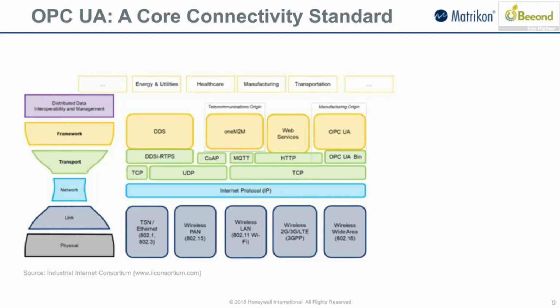And of course, there are different uses for different standards depending on what you're doing, whether you're doing fully engineered software systems, which would be more towards the DDS side, or you're doing more third-party ad hoc connectivity, which is typically what you see in plants and manufacturing environments, where you're bringing in third-party devices or systems or applications, and they all just need to start working together with each other. That's where OPC UA comes in.